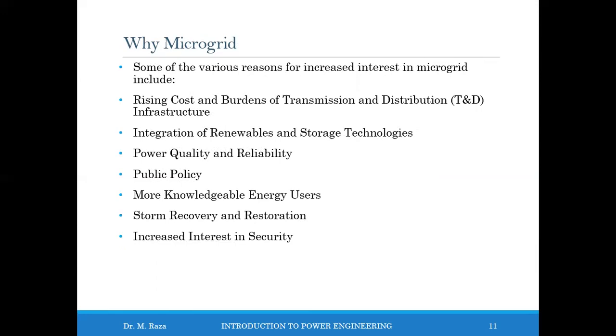Some renewable energy resources, most notably wind and solar, are intermittent by nature, which increases the voltage and frequency fluctuation on the grids. The risk is greatest when there is a high penetration of renewables. However, technology advancement in grid stabilization and energy storage have addressed these concerns in microgrid. Nowadays, the challenge of the renewable energy generation peaking not matching up with demand peaks can be resolved using energy storage modules.